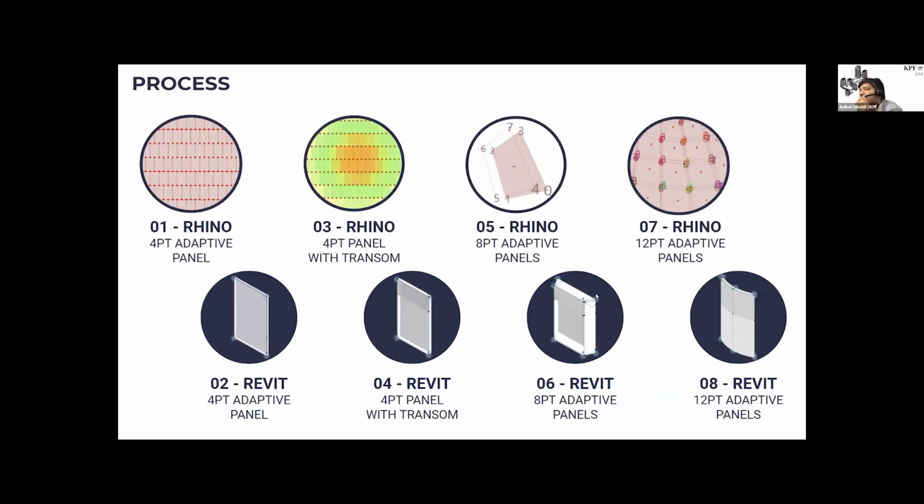As a very quick overview of the process, we're going to look at adaptive panels, Rhino facade division, and adding complexity to both Grasshopper, Rhino and Revit, ending up at the very end with a facade that has fully adaptive panels. We wanted to look at more of a real world example, but keep in mind this is more of planting the seed of the idea.